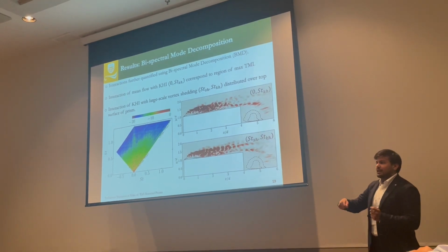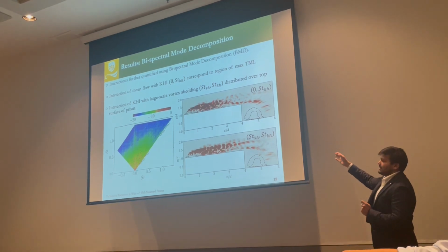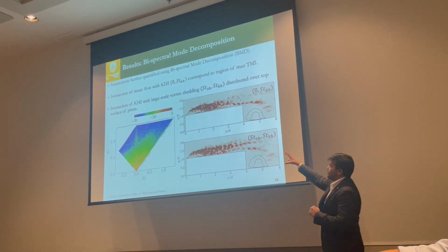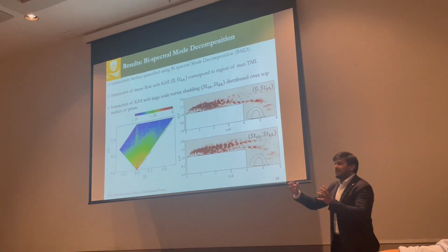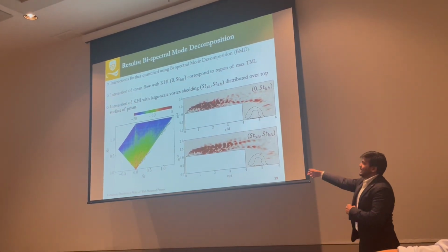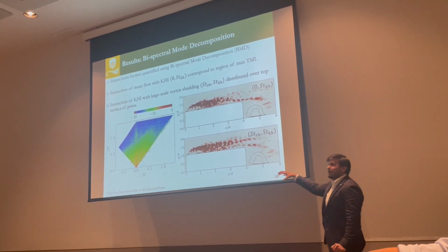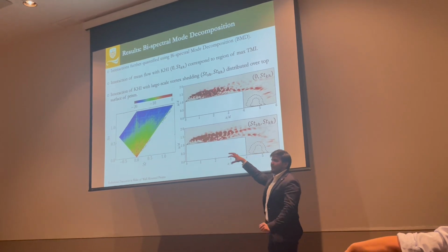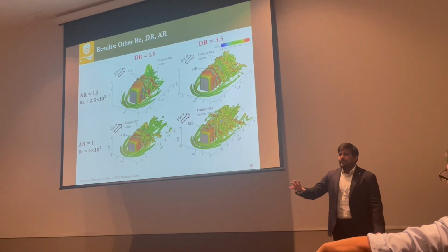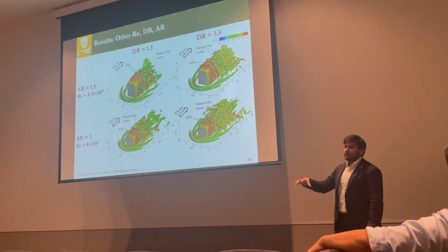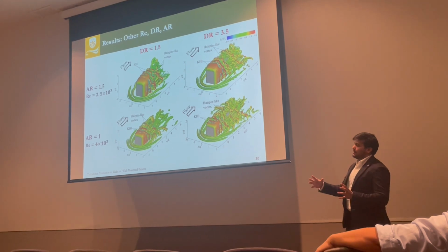So we specifically look at the interaction map for those two triads, and we find correspondence with the POD results from earlier. So in case of the interactions between the mean flow and the instability, we find the location where that energy is getting pumped into the flow, where that mean flow modulation is happening. While in case of the interactions between the instability and large-scale vortex shedding, we see the location of where the breakdown happens.